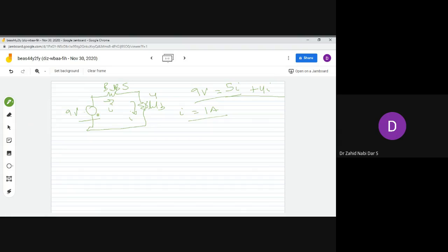See, basically this is minus plus, if I take this direction, so this is voltage rise. Whenever you have any doubt, you mark it as plus minus, plus minus. So remember, whenever you are connecting a battery to a resistor or any element, it always would be a fall. So across the bulb it would be a fall. If you have a battery, that's an active source, it would always be a rise, v rise.